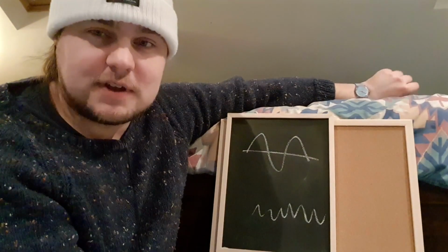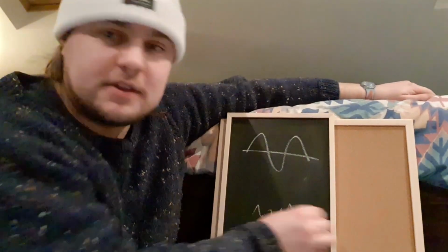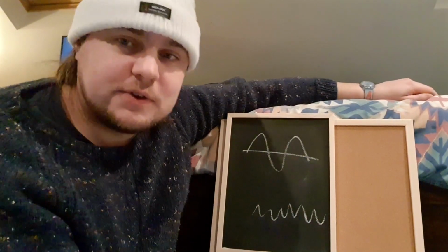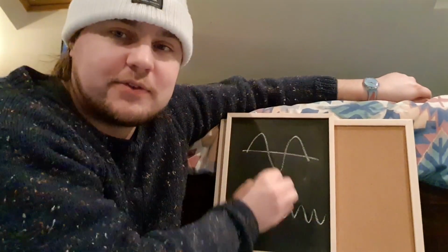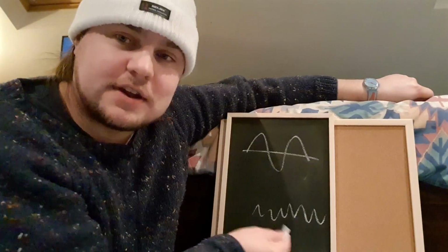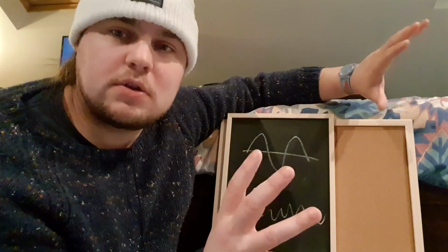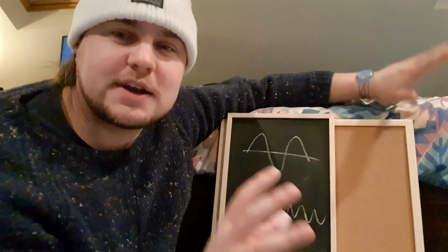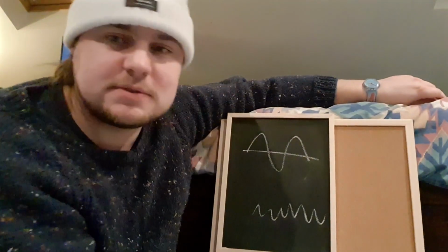So there's lots of filters built into all this electrical equipment to get rid of these harmonics. And the filters are tuned to a certain frequency. So if the main frequency slows down too much, the filter will be wrong and you start getting power surges that can blow things up. So basically the goal of the electricity network is to keep all the turbines rotating at the same speed.